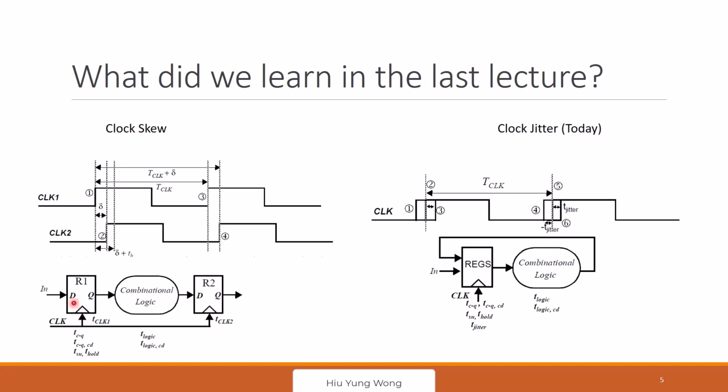When the clock comes up, I take the data from the previous block and pass it to here, and then I let it do the computation. And the result should not go through. For here, it already took the result from the previous computation and passed it to here already. Whatever you are doing here should not affect the next stage. So this is the ideal case.